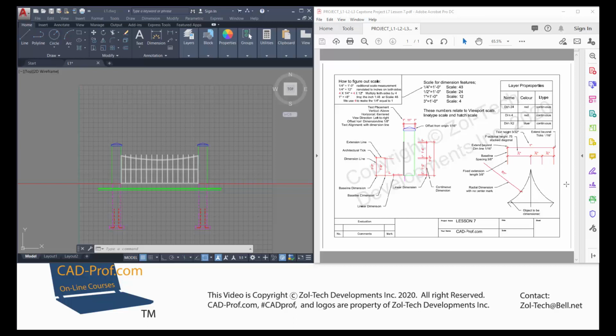When we refer to the dimension style, we're going to be looking at a number of items. These are referred to as arrowheads, even though they're architectural ticks. Anything that represents the intersection between the extension line and the dimension line refers to an arrowhead. And then we have information such as how tall is the text? What is the gap between the text and the dimension line? How do we treat fractions? Are they going to be stacked diagonally or vertically? And then we talk about text placement. Where is the text actually being placed? This series of instructions here directly relates to the menu, and again, that will become more apparent.